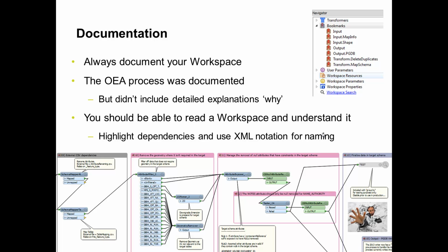Describe exactly what you've done, but why you've done it and why certain features are set up in the way that they are. Because if you refer back to this workspace in 2 days or 2 weeks or 2 years, you'll want to know what the subtleties or the nuances were with the data that meant that you had to go and take it through a particular routine. It'll allow you to understand that in a much better way. Here you can see that you can right click on a collection of features and add a bookmark. You can add annotation around features.